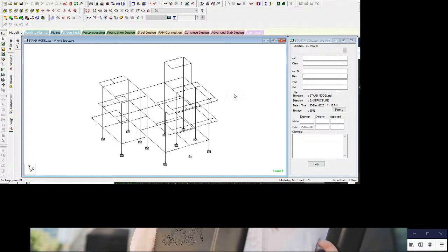So when the beam transfers the load to the slab, at that time you have to design that extra slab as a cantilever structure, because this is a cantilever slab, and the UDL load is coming on that particular point. So you need to take the moment, right? This is load into distance, that means you need to take that moment. Just 1 minute.